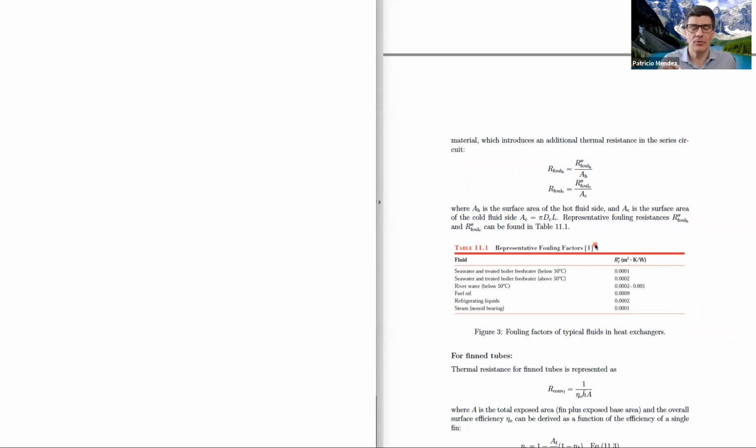And based on these calculations we're doing, we should be able to predict the maintenance schedule of a heat exchanger by knowing how the performance of the heat exchanger is degraded as fouling increases. These calculations, which we're going to do a sample of today, are extremely powerful. You can have a startup based on these things we're learning, because for the most part, people don't anticipate maintenance periods for heat exchangers. They just wait until it kind of sucks and then they deal with it. We can do so much.